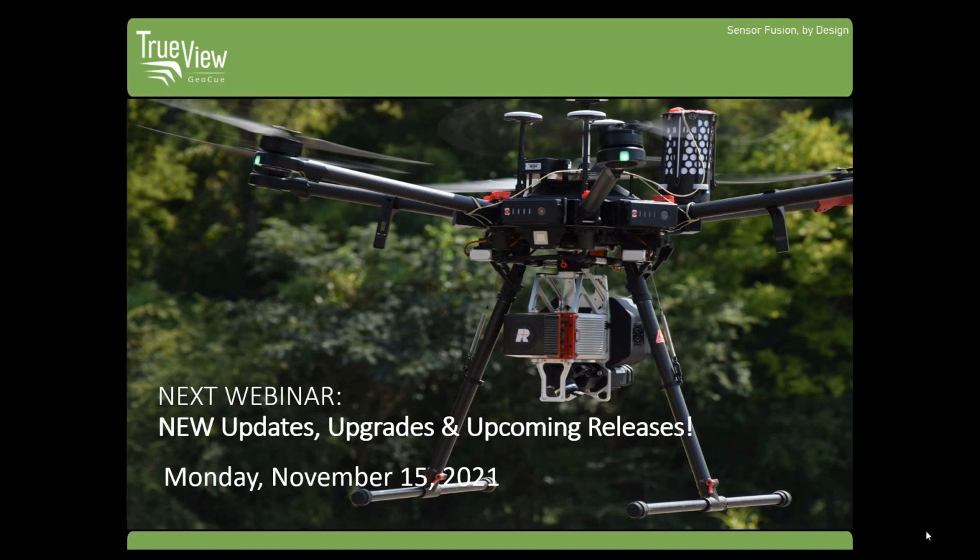But normally we say, with a 515, you're normally seeing better than 5 centimeters at 1 sigma, or network accuracy of better than 5 centimeter RMSE. Of course, with the Riegl line, the survey grade line of scanners, they're a lot higher grade scanner system, and so you're typically seeing 2 to 3 centimeters on those. Of course, that's our specs, and we normally see better than that when you actually process.